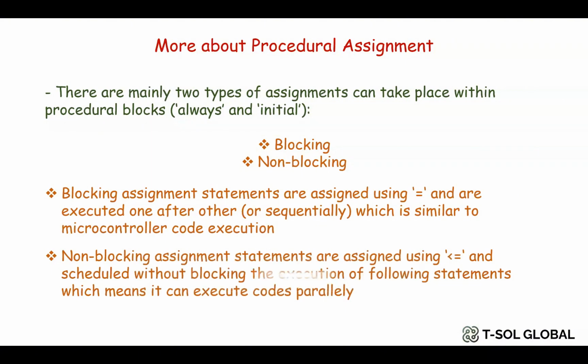And we have the non-blocking assignment. The non-blocking assignment statements are assigned using the less than equal sign, and are scheduled without blocking the execution of following statements, which means they can execute code in parallel. So the blocking assignments mainly execute the code sequentially, and the non-blocking assignments can execute the code in parallel.